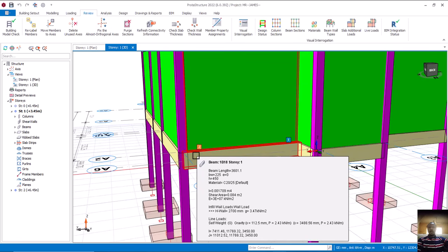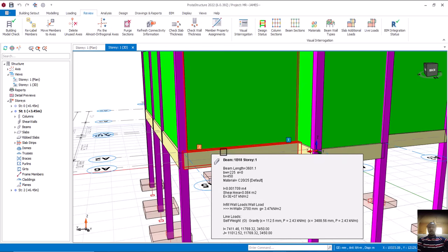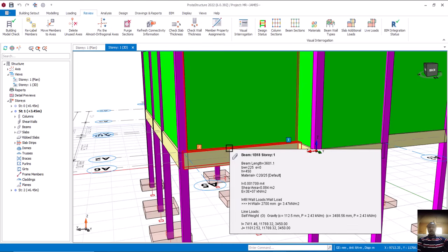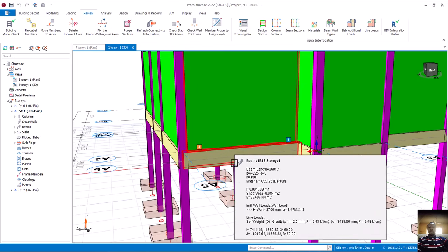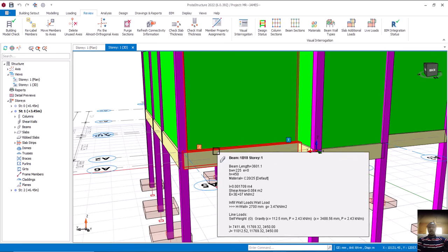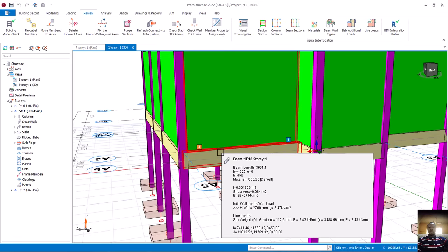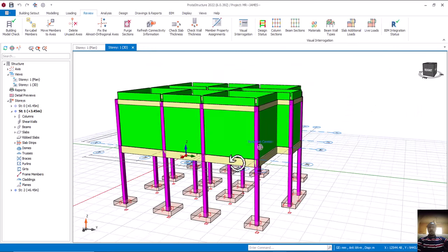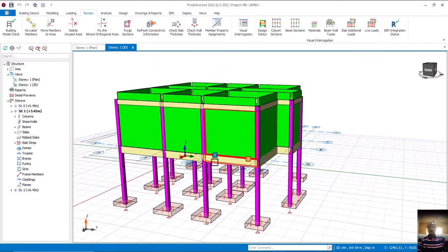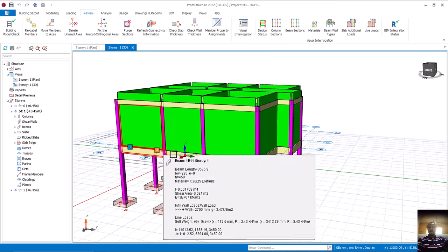No, you have no business with that. If in your drawing, what you are having on this beam is 2Y16 top and 3Y16 at the bottom, all you need to do is provide the same number of reinforcements you are seeing there on that particular beam label. Is that okay? And if this one is 2Y16 top, 2Y16 bottom, you are going to use 2Y16 top, 2Y16 bottom.